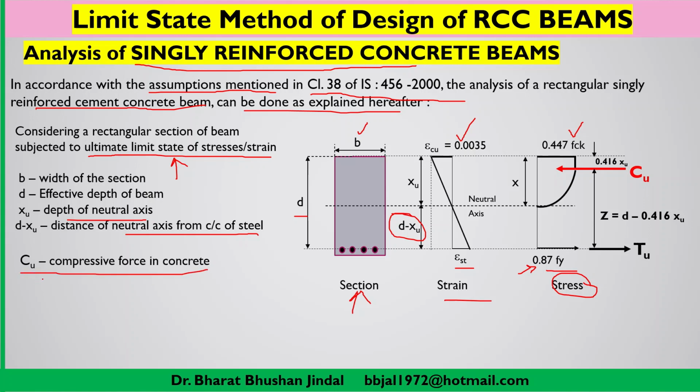So Cu is the compressive force at the stage of the ultimate limit state. When the ultimate limit state is reached, Cu gives you the value of the compressive force in concrete, and this acts at the center of gravity of the stress block, where the whole force will be acting. As per the mathematics, which is not in your scope, you have to remember this formula, and all the information is given in the IS code.